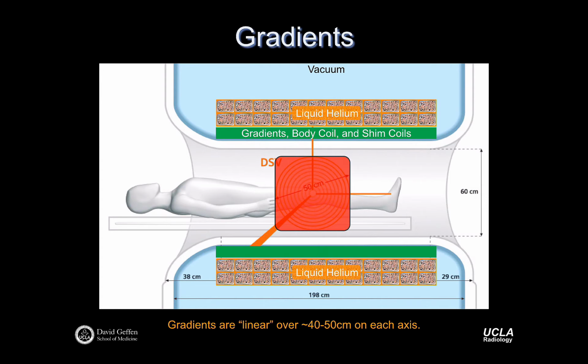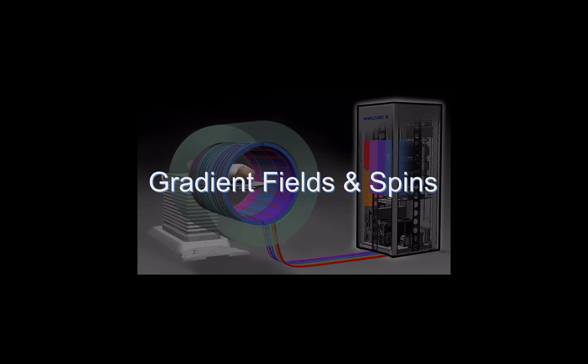So the whole MR system is really designed to have highly effective uniform fields of all kinds right at isocenter over that approximate volume size. This is how, in the background, you can see how the whole system comes together. You'll have an MR room where the coils themselves lie. Those really giant copper cables, as big as my fingers, run through the ground or the ceiling out to a room outside of the MR suite. And these are the gradient amplifier cabinets. They're not noisy themselves, but a lot of the water cooling is happening there. That's where the power supplies are found.